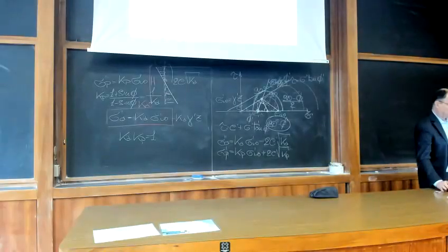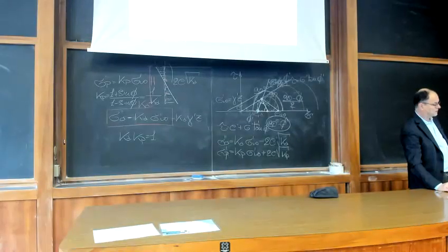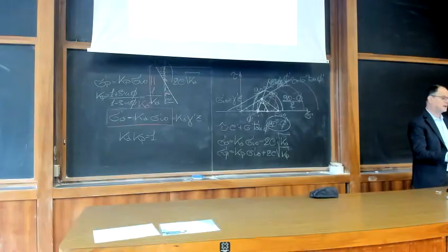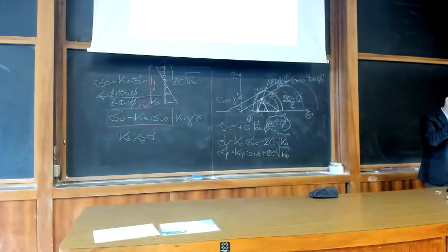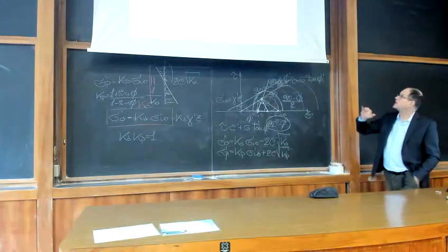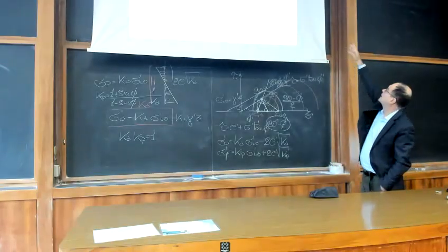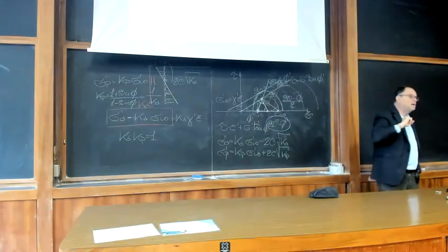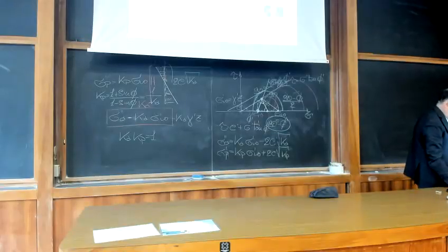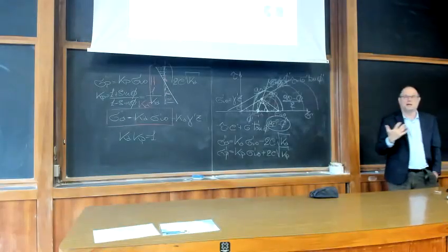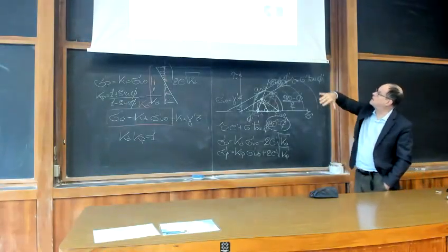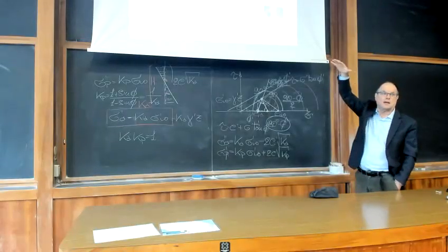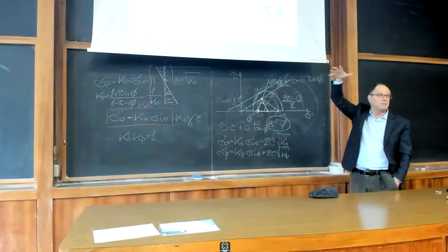In the previous slide, this was a qualitative diagram to separate ultimate limit state from serviceability limit state. And I said once you reach an undefined settlement, you have reached bearing capacity, bearing resistance. In reality, this is the graph that you get. So your curve never reaches a horizontal limit.